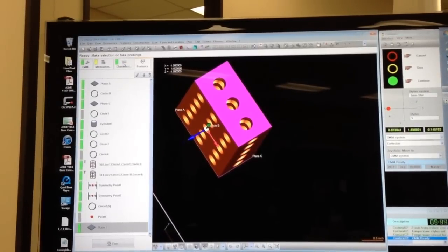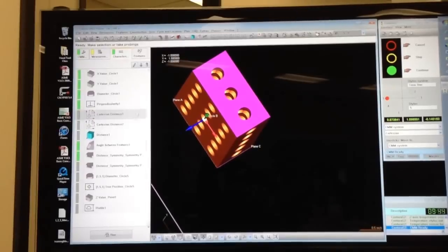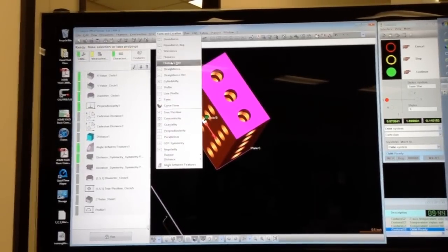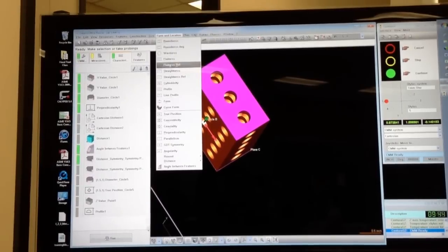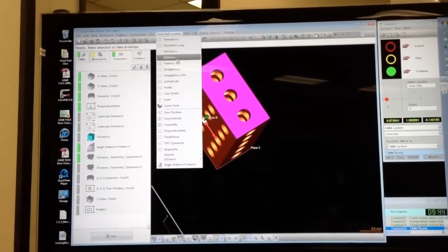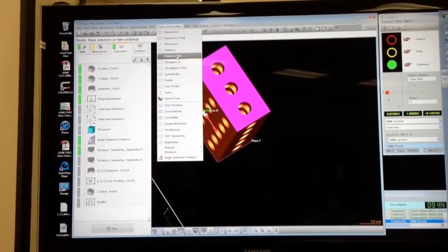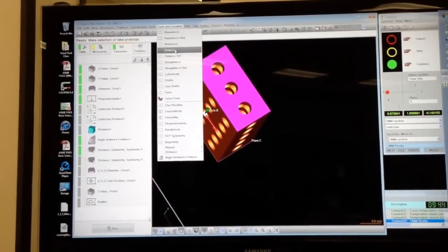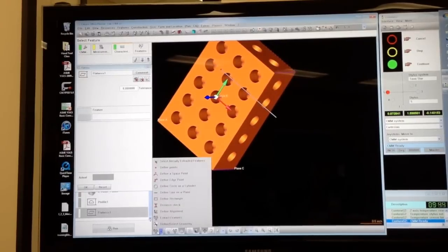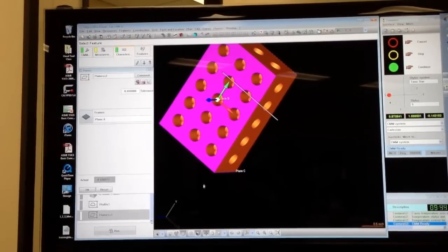And looks good. The final characteristic in fact uses the first feature that we measured as part of this program, and that's the flatness of the primary datum. You'll see under flatness that there are 2 types of flatness. Normal flatness is this first one. The second one is when you have flatness with a reference length, 1 thou per inch, for example. We'll choose regular flatness, open that up. Again, I'll switch to the Select Already Extracted Features and get the top datum plane.